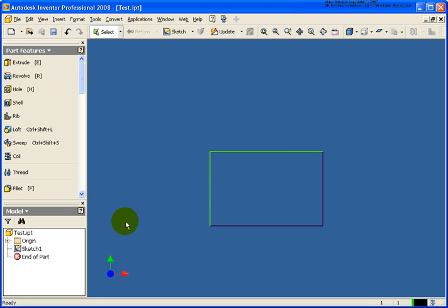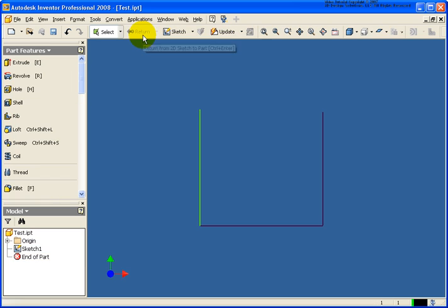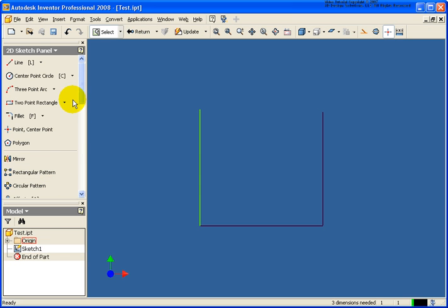Now there's 2 ways of doing that. I can click on the Sketch tool, click on some geometry in the graphics window, or click on Sketch 1 in the browser. And you'll notice all of my tools are available here. I can grab one of those lines, erase it, drag and pull whatever else we need to do. So let's do this one other way. I'm going to click Return. That will also exit me out of that sketch environment. I can also just simply double click on Sketch 1 in the browser to make that active.